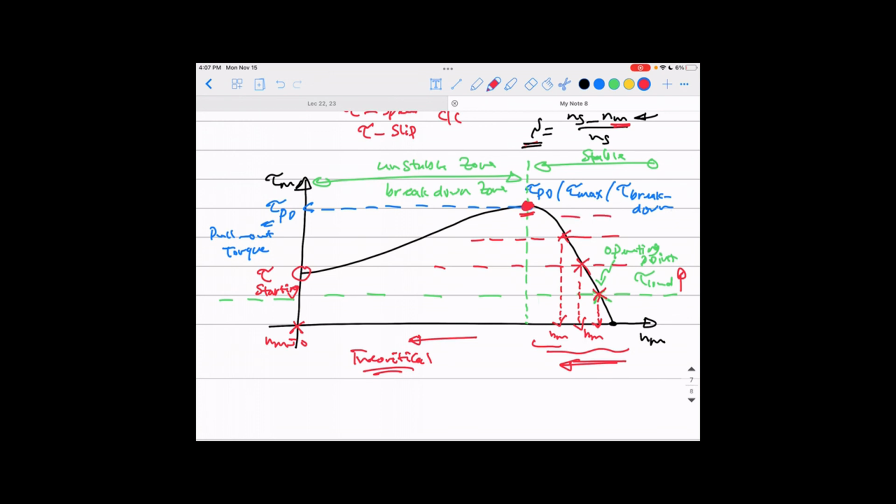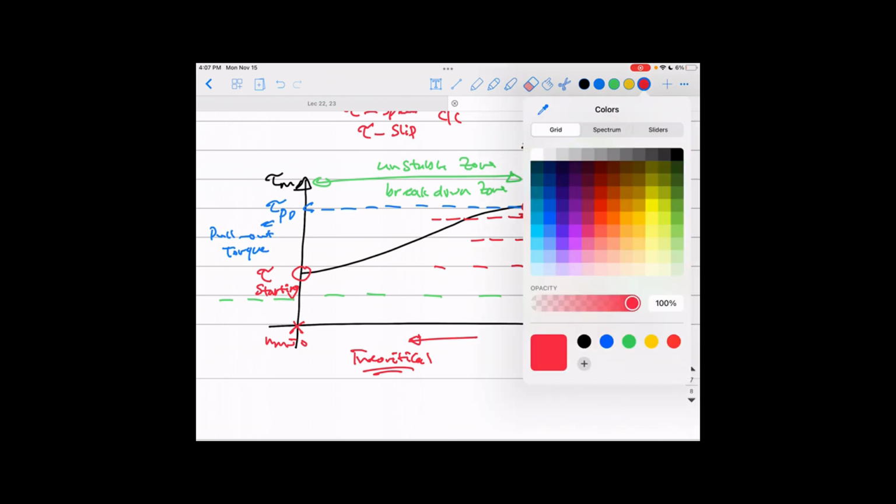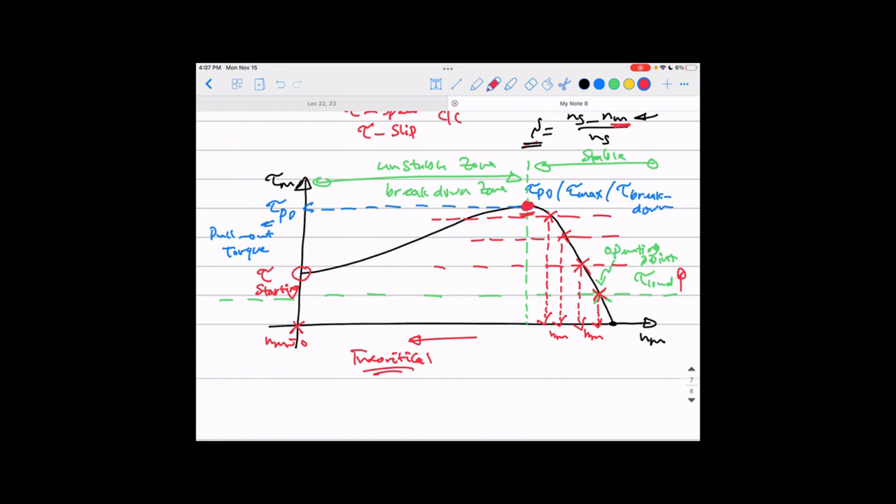And if you increase the load torque more and more, you will hit this point, and you see the speed going down and down. Okay guys, like you've seen here. So with the increase in the load, the speed just keeps decreasing like that until you hit the maximum load, the pull-out torque, and this gives you the corresponding speed.